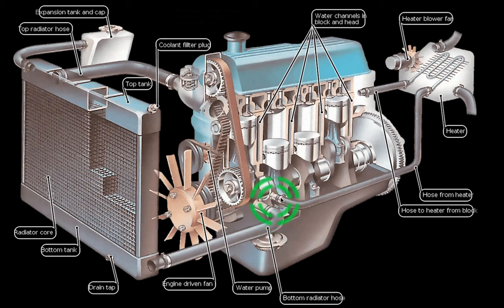How it works is there's kind of a wax inside that starts melting after certain degrees. Maybe you can look it up on Google. It's made in such a way, with a certain mixture, that it starts to melt at 88 degrees ideally, and then it allows the water to start flowing inside.